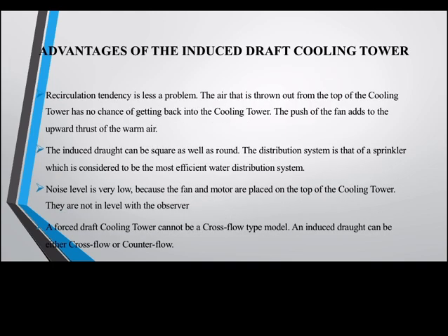So let's talk about the advantages of the induced draft cooling tower. The first one is that recirculation tendency is less of a problem. There is no air from the atmosphere entering back into the tower since the fan at the top is drawing air at high velocities, and the atmospheric air is at a very low velocity.